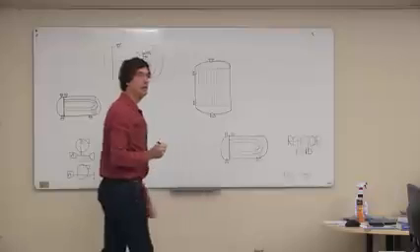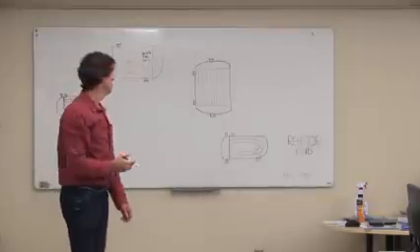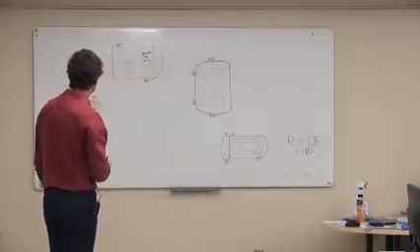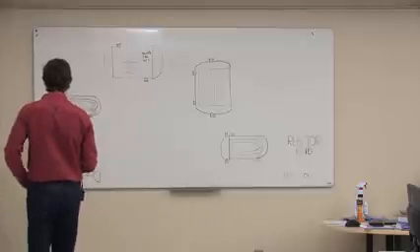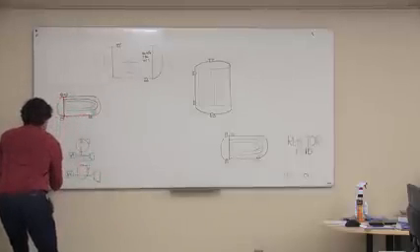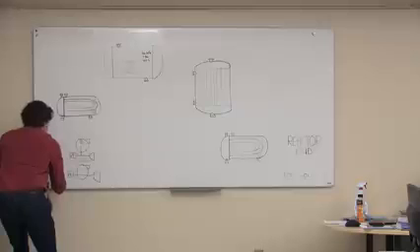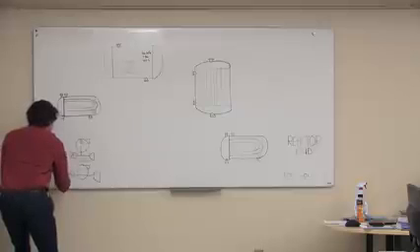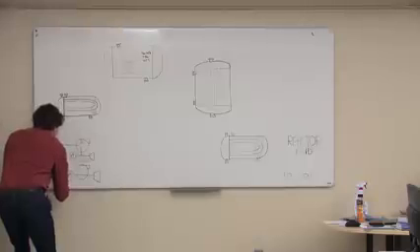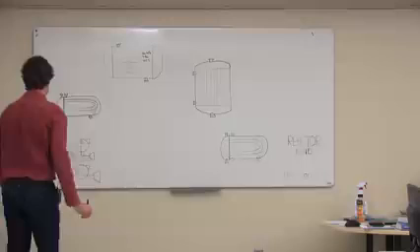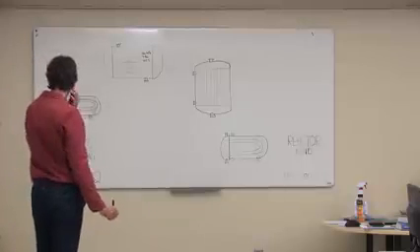So it's really just a question of piping it. Seems pretty straightforward. So we know we're going to have boiler feed water coming in the side of the drawing here. It's going to come in from a utility P&ID, so we don't need to show the drawing number for that because we haven't drawn the utility P&IDs yet. We've got our boiler feed water coming in here.